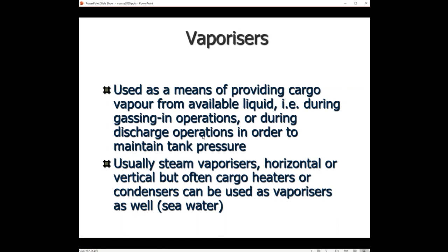Or when the cargo received from shore during loading is below its boiling point, that might create a negative pressure in the tank, then we urgently need a huge amount of vapors. We will start up the vaporizer. So there are a few situations where we will need a lot of vapor, and then the vaporizer is our help.